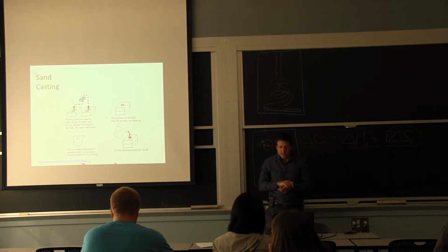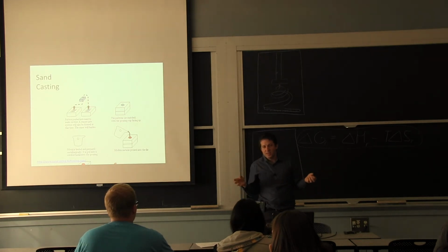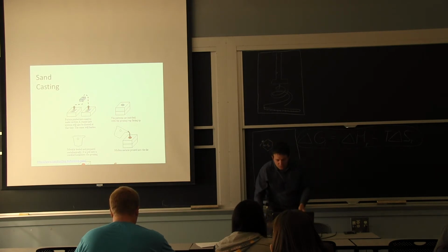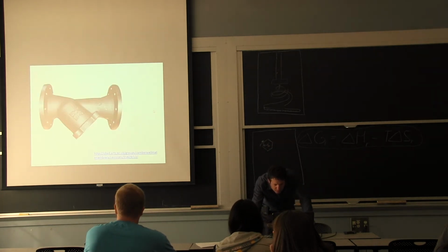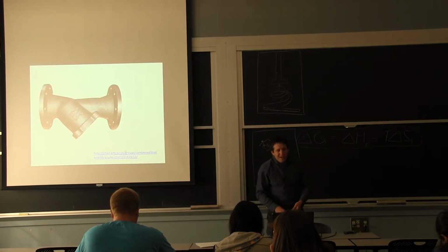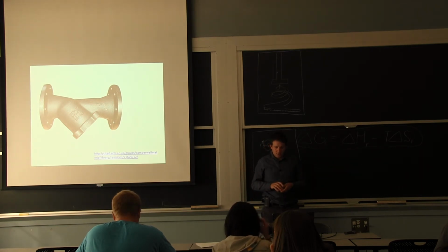When you're done casting, your consumable generally is gone because it went through such a thermal cycle when you pour the liquid metal into it. Plus, you need to get your part off. So in the end, you separate everything. Realize now we're setting out all the final processes. But it's not a very advanced process. It's relatively inexpensive. The mold material costs nothing. And you can do batches and make these trees that are shown in one of the initial images.